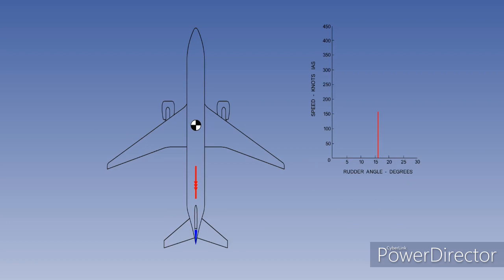The rudder on any aeroplane must be powerful enough for the worst case event. For the rudder of a large modern jet transport aircraft, the worst case event is an engine failure at low IAS. At other times, however, that much rudder power would be excessive, so large modern jet transport aircraft are fitted with a rudder ratio changer. The illustration shows a large modern jet transport aircraft at low IAS. Full rudder pedal travel has resulted in maximum rudder displacement from neutral. In this example, we assume the pilot is making a maximum rudder command from the flight deck.